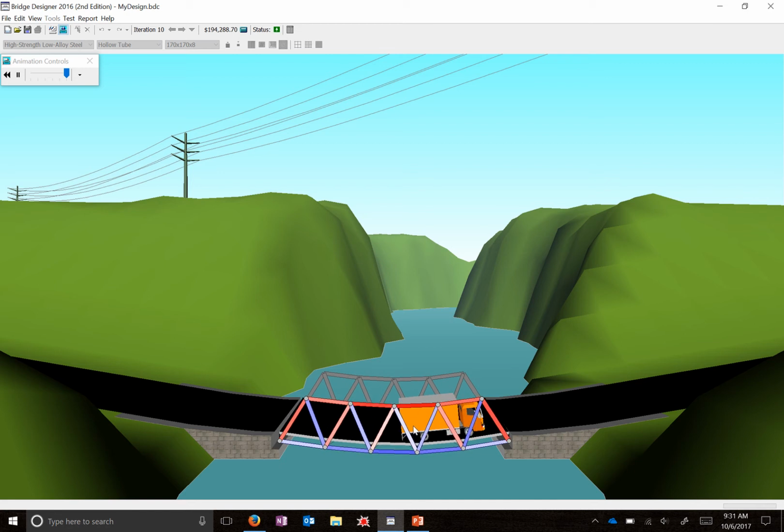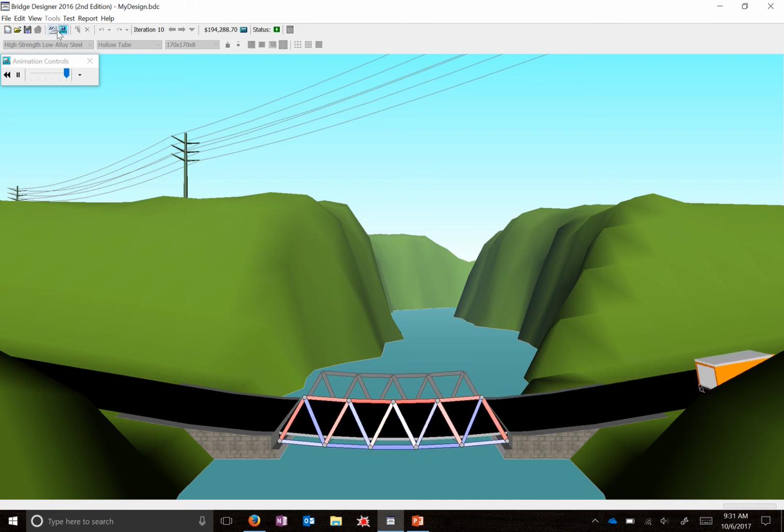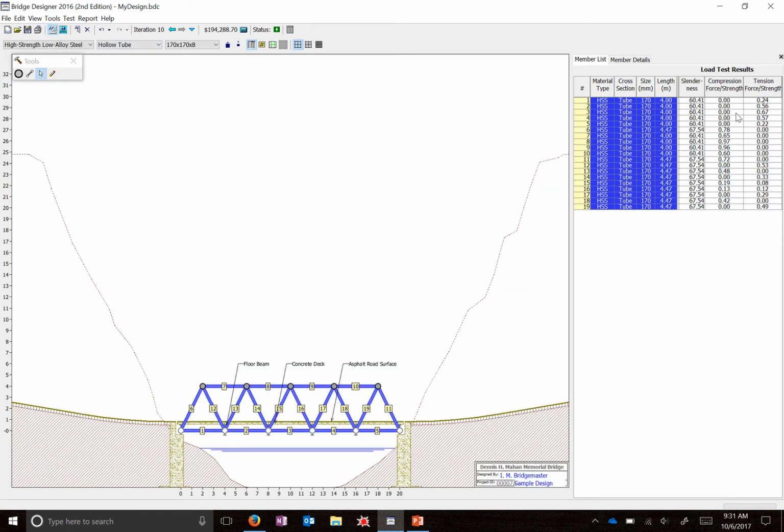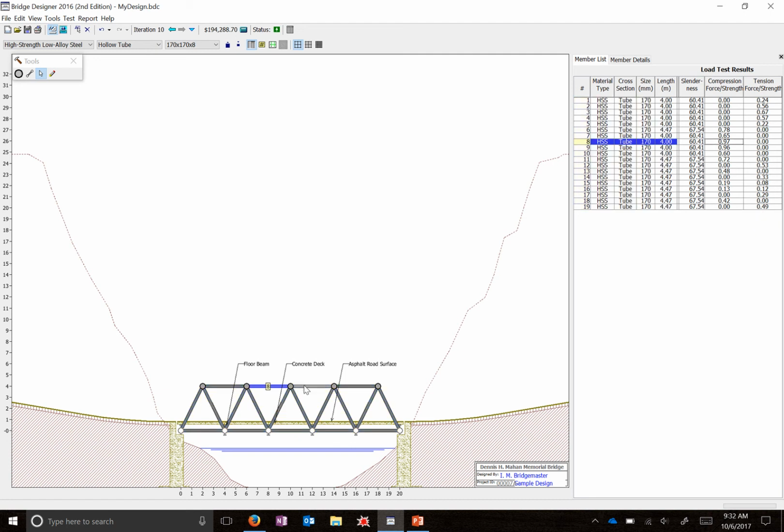It's got a lot of parts. It underwent a lot of stress there. So we'll check. This is about as good as we are going to get on this particular bridge. We were at 0.97, 0.96 for compression on those center pieces. So if you click on that, that is 8 and 9 are at the 0.97 and 0.96.